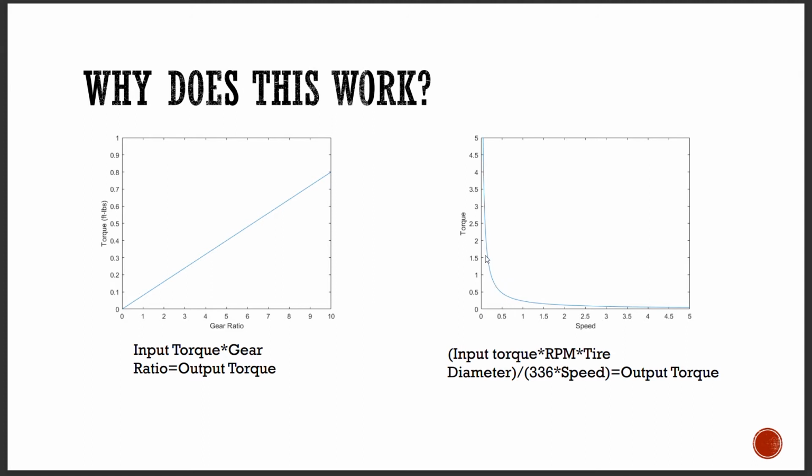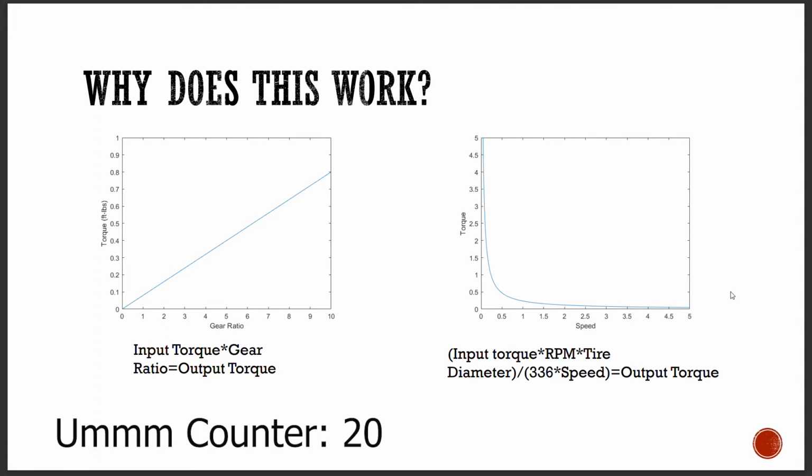Well, with our lower gearing and at a lower speed, we're going to want the higher amount of torque given this function. So we're going to want first gear. But as we increase our speed, we need less torque, but we need higher RPM. So in this case, we're going to shift to second, somewhere in here. And so then in our final overdrive, which is at 3.5, we're going to be in our highest gear and our lowest amount of torque.